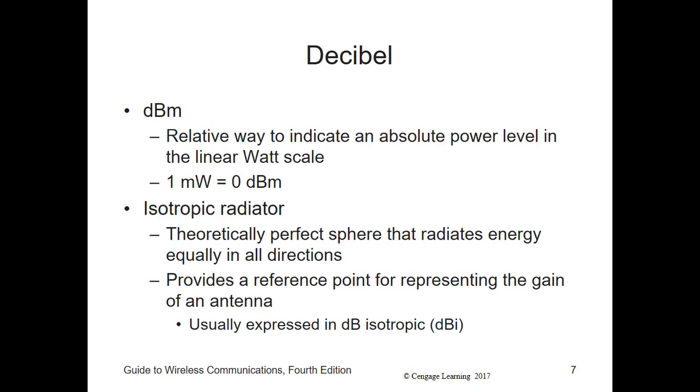Okay? Using dB to represent gains and losses means that the only types of calculations required are simple additions and subtractions. There's no need for multiplication, division, or any other kind of complex calculation to convert the values to the same unit in order to get a meaningful result.